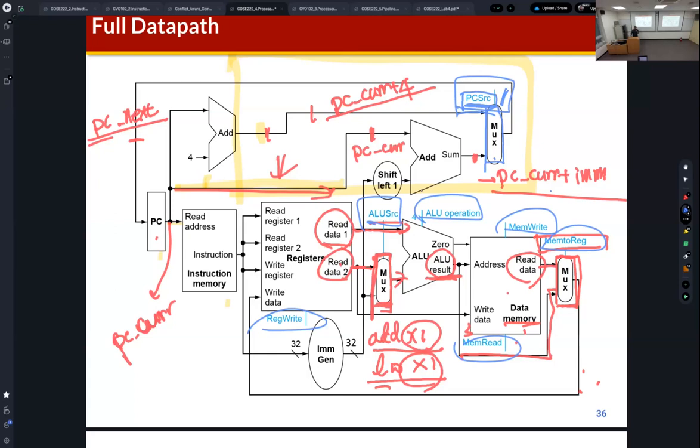These are control signals, right? So what are control signals? The control signals determine the operation mode of the data path. For example, think about the read write signal. If read write is 1, then the register file writes data, which means the data is updated.